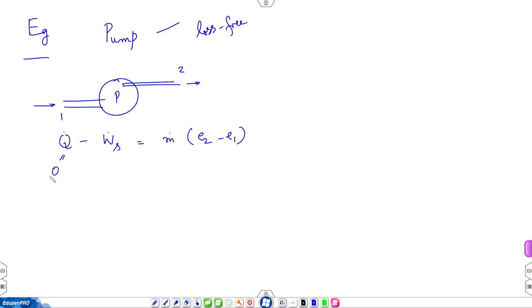Okay. And that E2 minus E1 taking place in a tube is also referred to as the loss taking place in the tube. Is the energy loss in the tube. So, now the tube lengths are small. So, there is no loss in the tubes, pump is taken to be 100% efficient. So, there are no losses inside the pump.